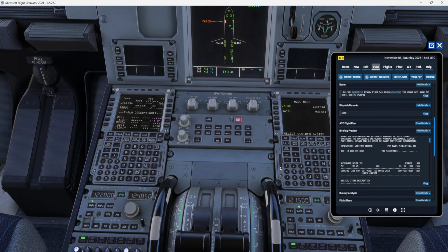Then return, second flight plan, clear, and here we have it. Then at PD02 we hold, and we make a course of 353, right turn, and then we compute. Here we have it. Then we go to flight plan, LFLL, fix info, LFLL, runway 35 left. We are going to have radial of 353.